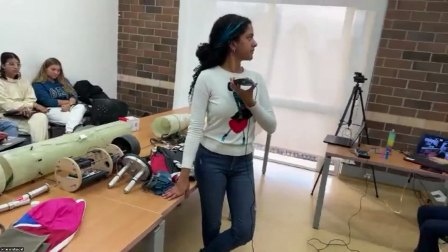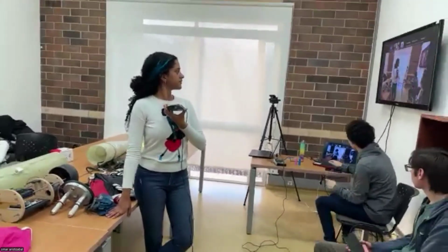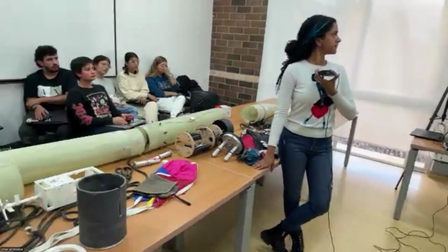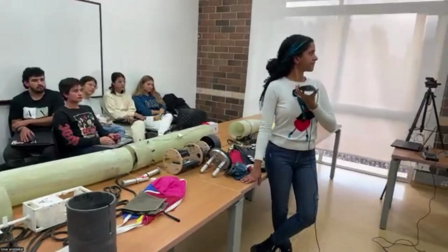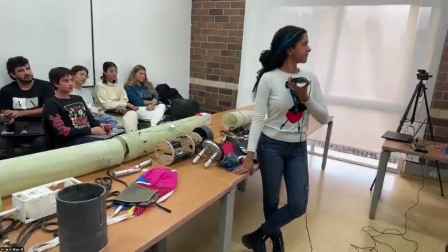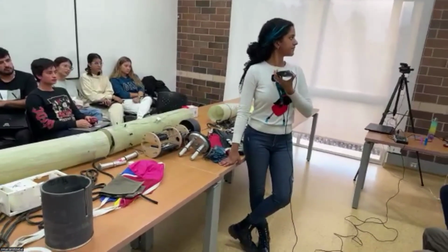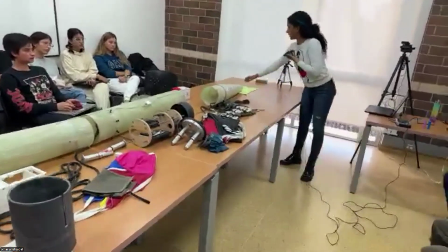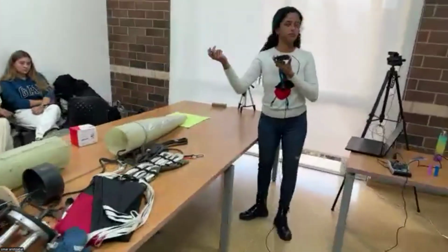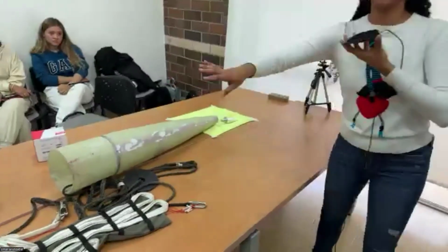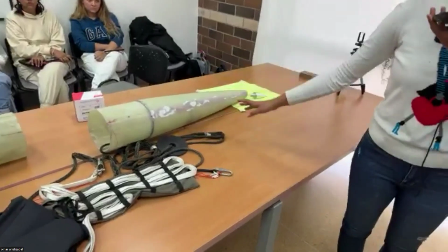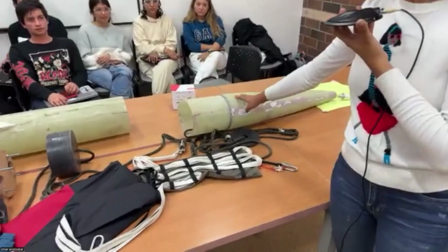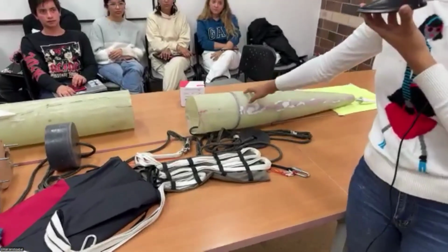It seems like your avionics bay has most of the weight towards the front of the rocket, but it's not quite as high in the rocket as I would expect. Well, given that we also have a very robust metal nose tip, it also adds weight to this upper front part of the rocket. Also, the nose cone is a little bit heavier than we expected, so that also helped us with that stability.